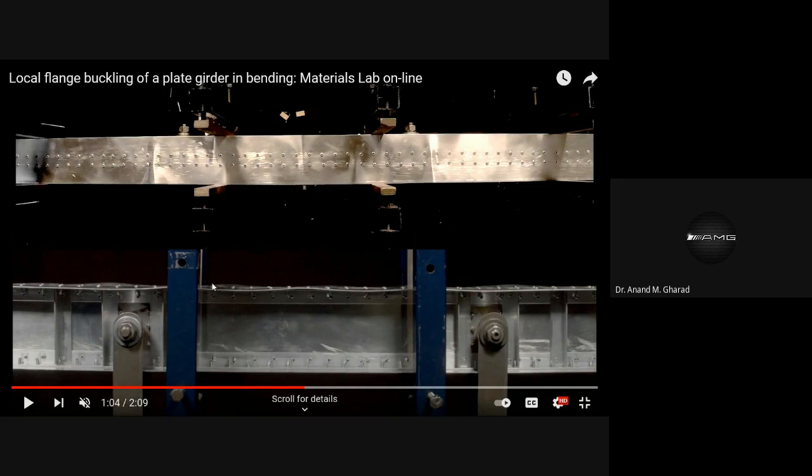And in beams, especially the steel structure or the structural steel, you will find such kind of phenomena to be very predominant, and this is known as local buckling effect. This local buckling you can observe not only on the top flange, but with the increment in the loading, you may even observe it in the bottom flange of the I section. So have you understood this?